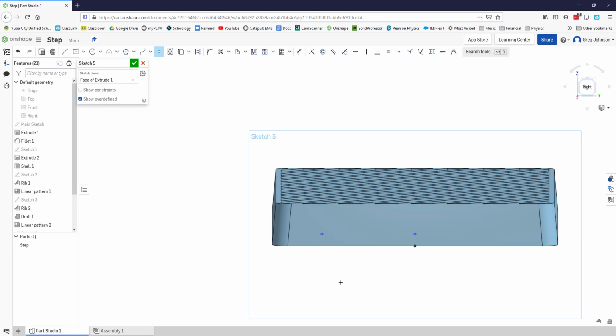Okay, so now the dimension from here to the bottom is supposed to be 20. So click on the dimension tool, click on the point, click on the bottom edge, and we'll make that 20. And you notice that one raised up because they're tied by that horizontal constraint. And then I'm supposed to make, it says the 50 millimeter dimension is to the virtual sharp of the filleted